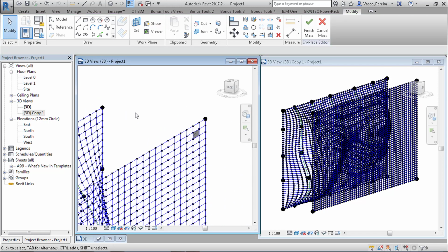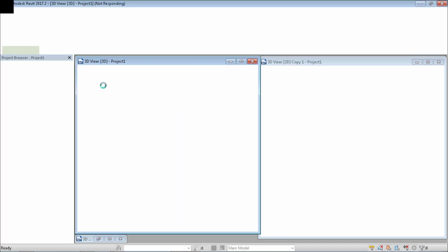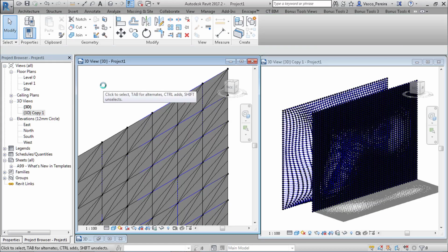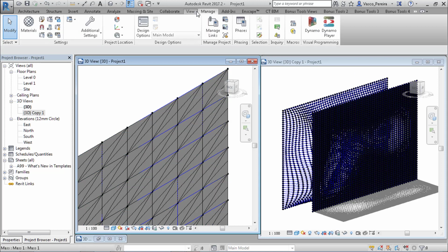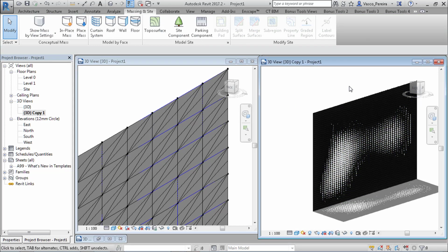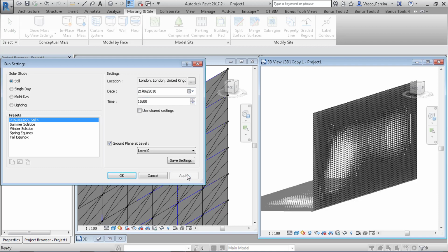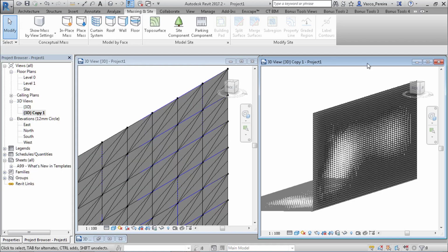So if I hit repeat, it may take a little bit because I divided the surface too much, but you will see that what we got is a pattern that's not changed only by distance to one point, making just a circular pattern effect, but something a lot more organic. So quite interesting. Now all we have to do is just play with the surface behind and make as many lumps as we like, or make this change more gradient, however we like, just by changing our surface.